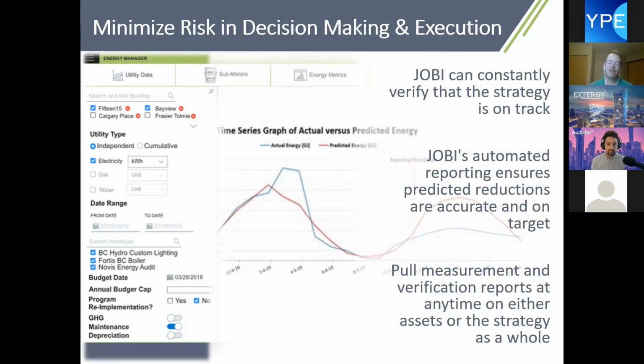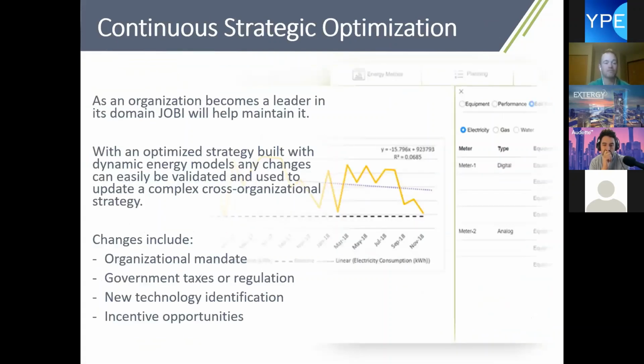So when you go to your client, you can obviously suggest that they put in submeters and get that really high accuracy data. If they don't have the money, and we're talking about a small 40-unit multi-unit residential building, they're not putting in submeters, we can use these virtual meter points. Saves a massive amount of money. Obviously, we lose some accuracy in the data, but it gives them enough accuracy in order to make decisions around what should be happening.